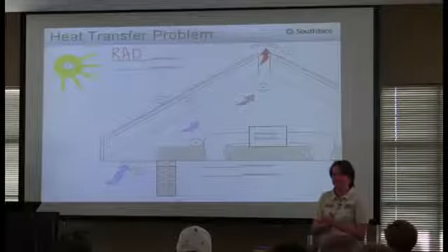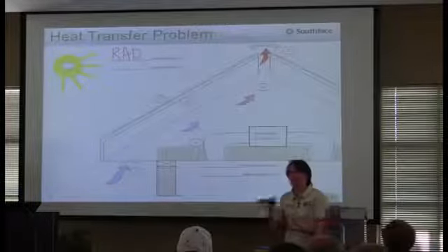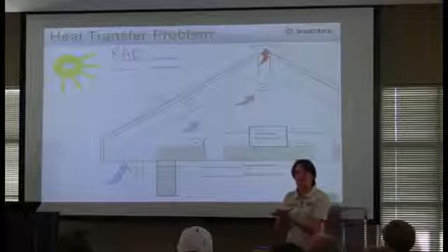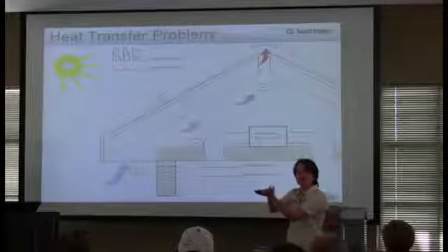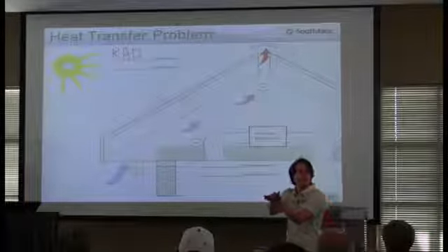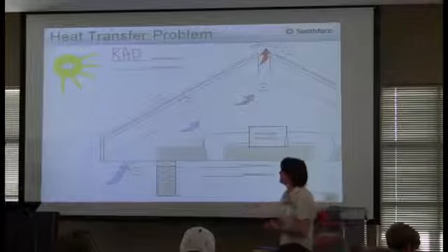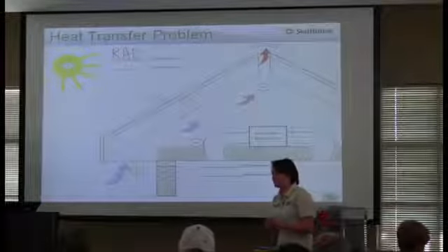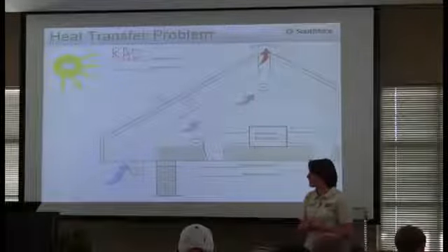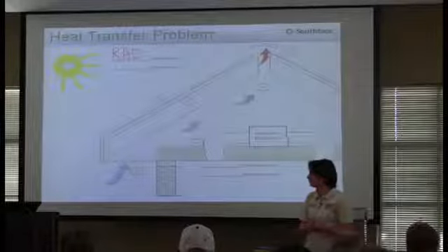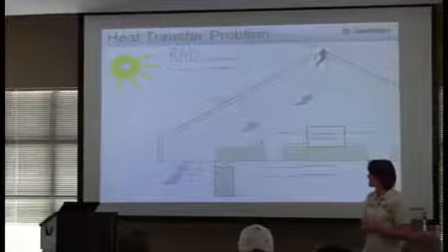So from 1 to 2, as Mike has already written in, what kind of heat transfer is it? It's rad. It's totally rad. From 2 to 3, so from the shingles to the underside of the decking, what is that? Those are in contact, right? Conduction, because they're in contact, remember? And they're solid materials, right? You're conducting through the 1/2 inch of OSB, or the plywood. That's a solid material. Does that make sense? Okay, so that second answer is conduction.